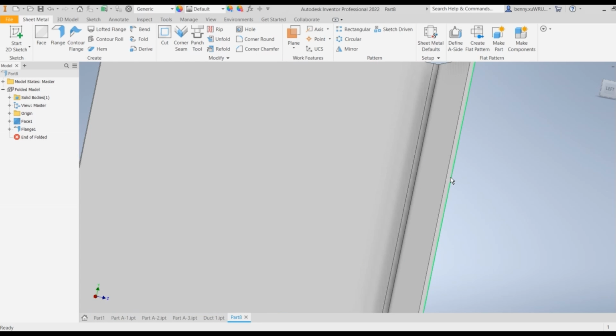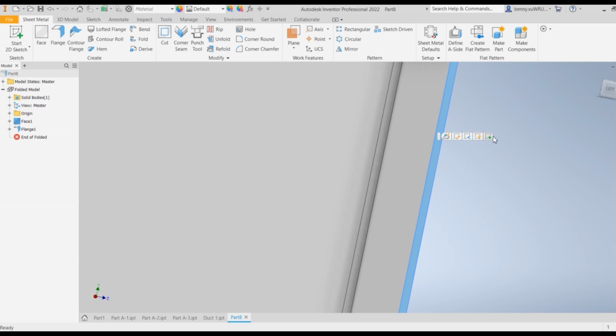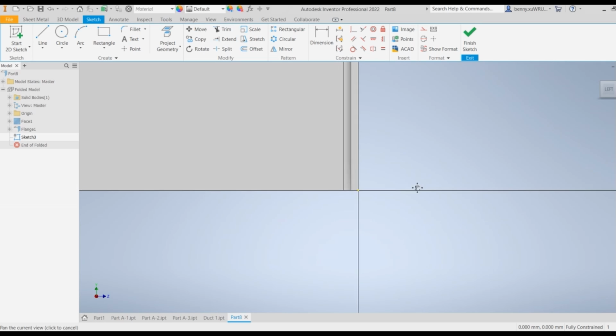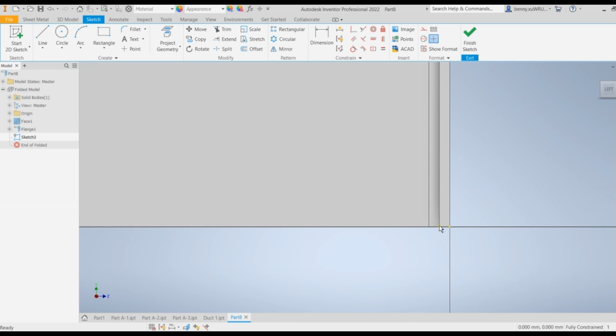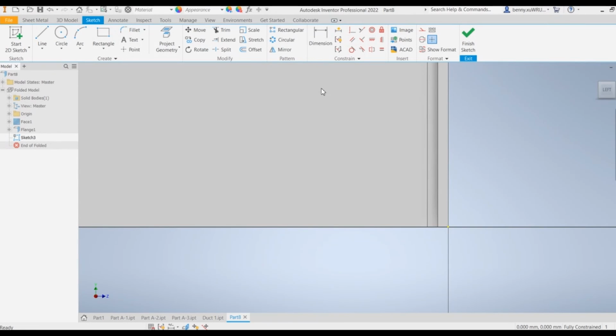And then I would like to select and start draw. Remember the start point should be here. Okay, same as the other one, go to rectangle and my start point from here. So the first thing I do is 214, tab, 250.